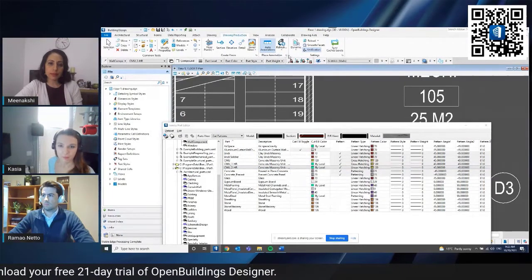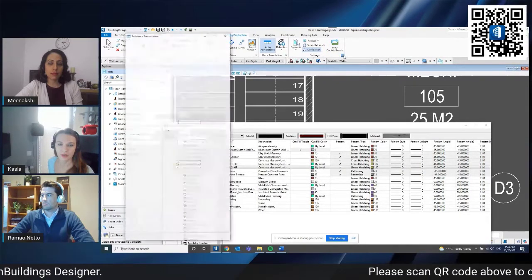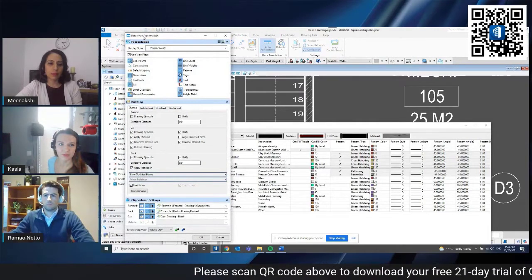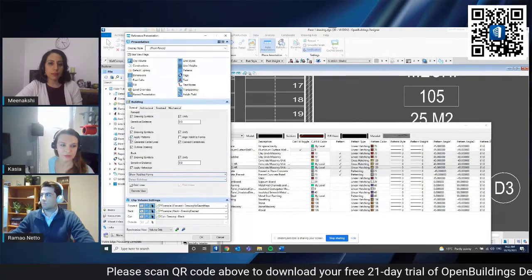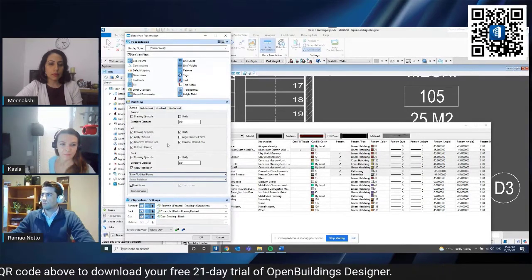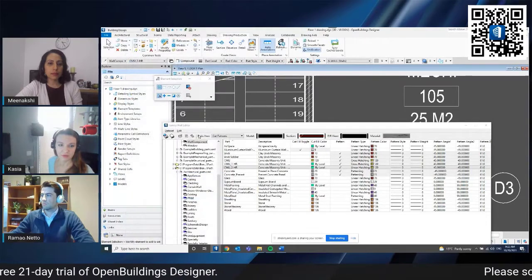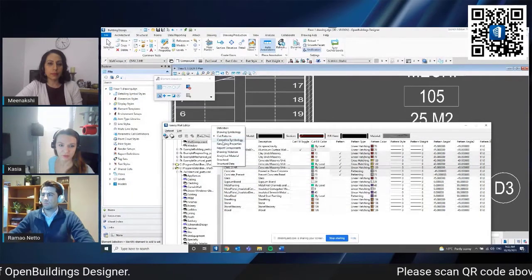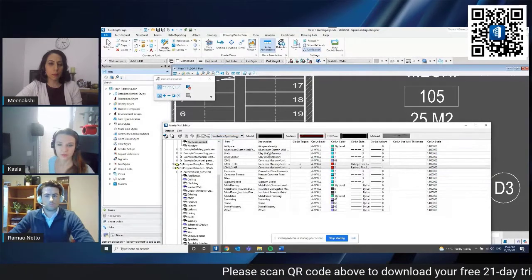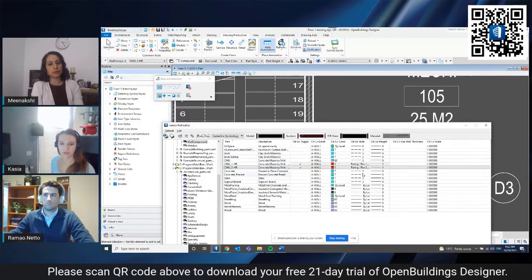I've just mentioned that for patterns, we need to take care that in the reference presentation dialog, we have this apply pattern toggle switched on. And the same for the center lines, because we can also control the center line symbology. We can have a look here, center line symbology as well for the walls, so we can decide about different types of this symbology.